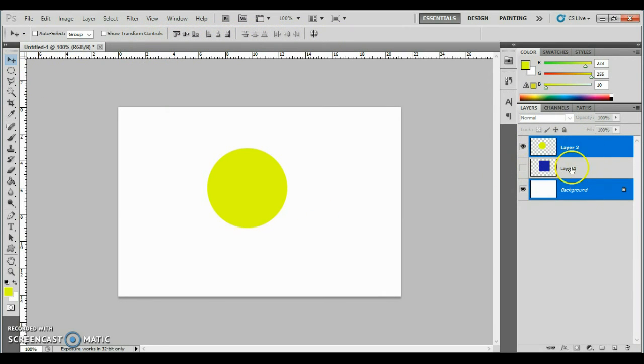So let me select two layers, one is the background layer and the second is layer 2. These buttons are activated. Let me click on each button so you will see what is happening. This is vertically center now and vertically going to the bottom. This will go to the left, this will come to the center, and this will go to the right. To center on the page, you can select horizontally center and vertically center. It will be centered to your background.